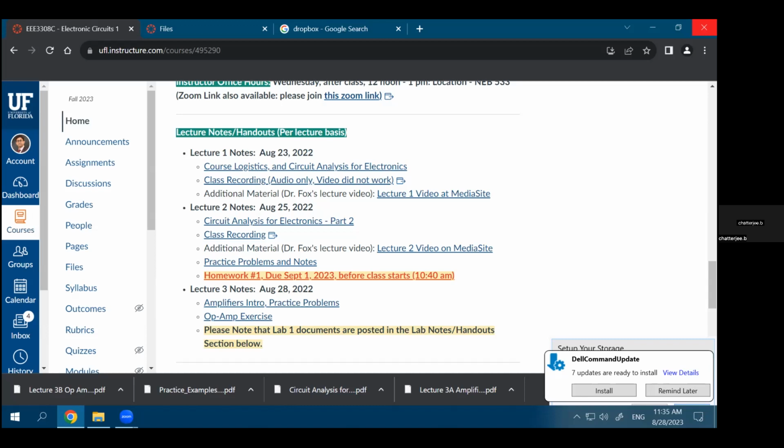So you might see in the lab that some components will work even if you don't apply a DC bias. But those are components where you have a VDD of, let's say, plus 3.3 volts and a VSS of minus 3.3 volts, so the average of that is near 0. The DC bias means that the average or the DC point of your input has to be the average of your VDD and VSS. So those components which have a VDD and VSS of plus 5 and minus 5, or plus 3.3 and minus 3.3, will work even if you don't provide an input DC voltage, with your input DC voltage equal to 0. But that's just an effect of the fact that your VDD was plus something, your VSS was minus something, and the average is 0. That's why it works. It does not mean that it can work with 0.